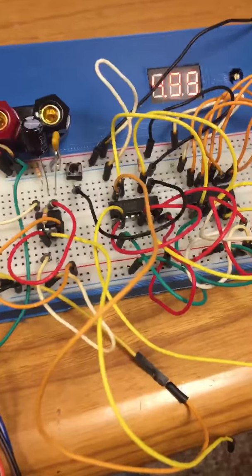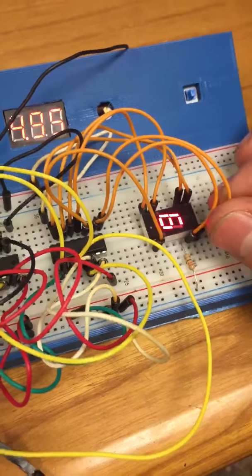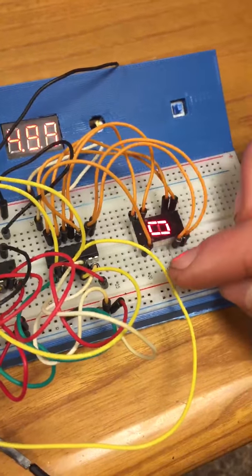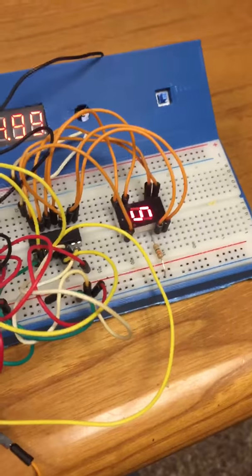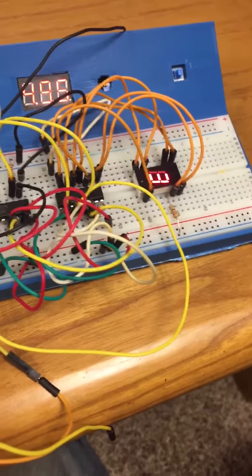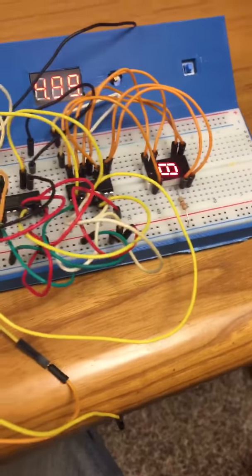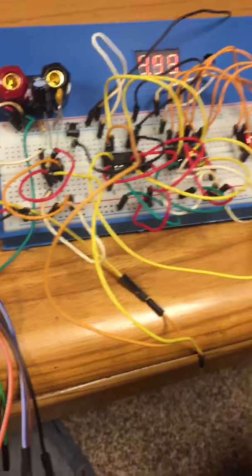Everything was pretty straightforward, just a bunch of jumpers. The only modification I made from the instructions was, instead of having a resistor for each one of these, I just had a resistor pulling it to ground there, because that still limits the current, so it doesn't damage the display. It's just much simpler. Originally I tried setting it up with 7 different resistors, and it got really messy and cluttered, so I decided to go this route. Hopefully that's okay and doesn't negatively affect my grade.